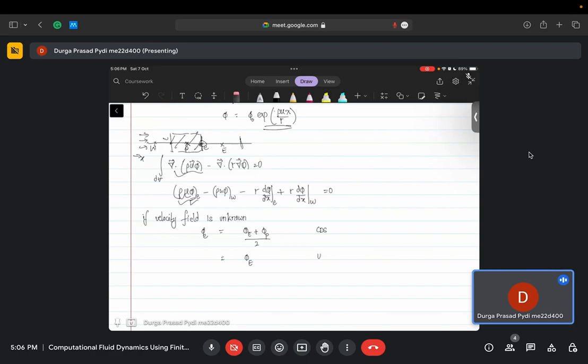This is in the upwind scheme. If the flow is in the positive x direction, it will be phi capital P, and if the flow is in the negative x direction, then information will be coming from the capital E, so phi east will essentially be phi E. This is the upwind scheme.